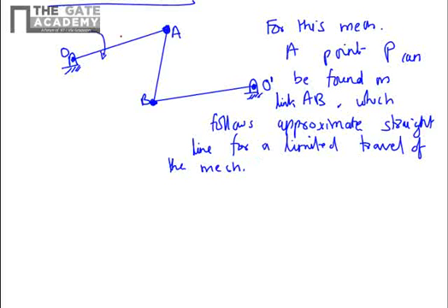So you can have the rotary motion input from the link OA, this can act as a crank, or you may have it from the OB also. So OA or OB is the crank, and you can find a point P, not all the points, some points based on some geometrical derivation that you can find in a textbook, that it follows an approximate straight line over a limited period.